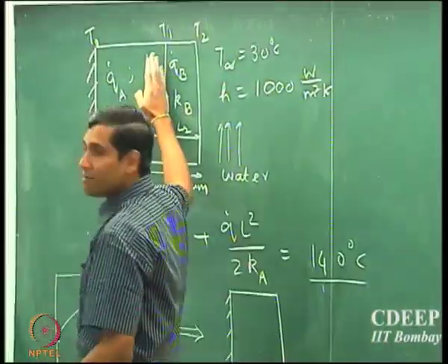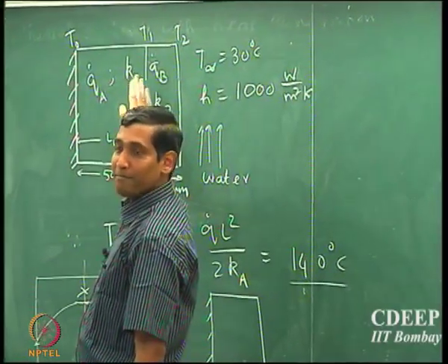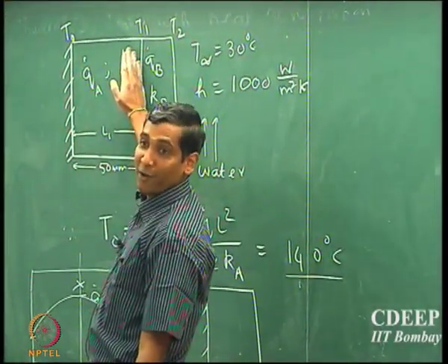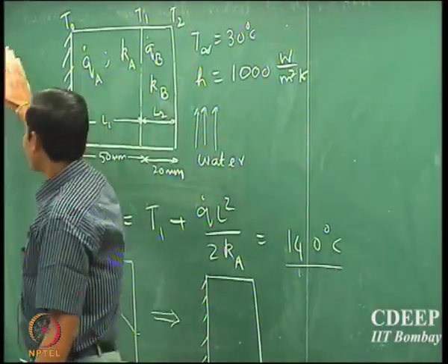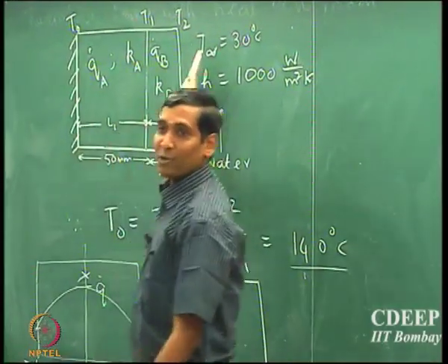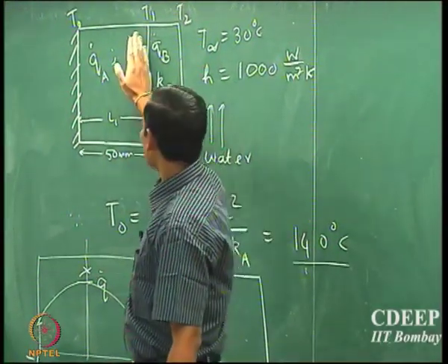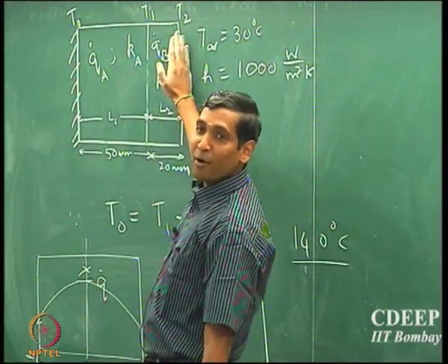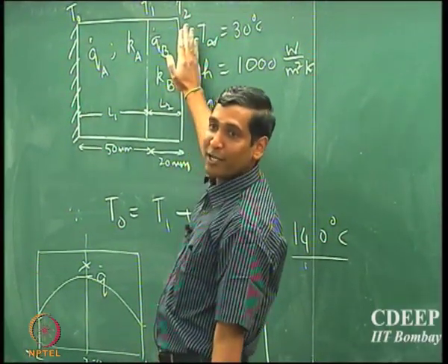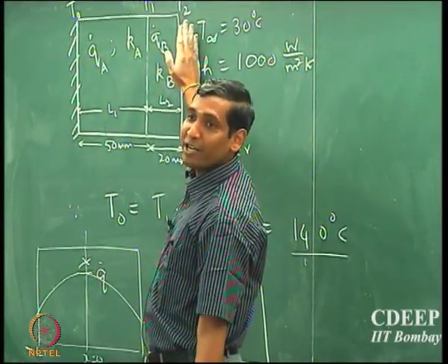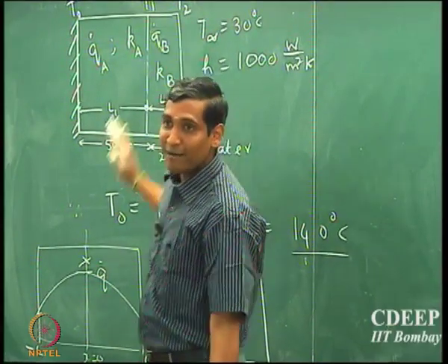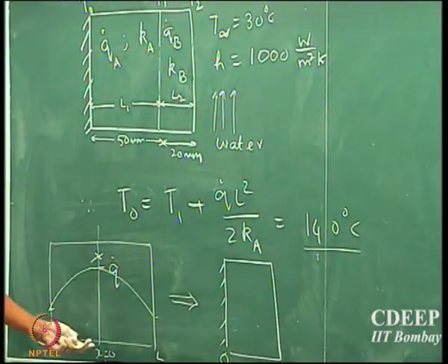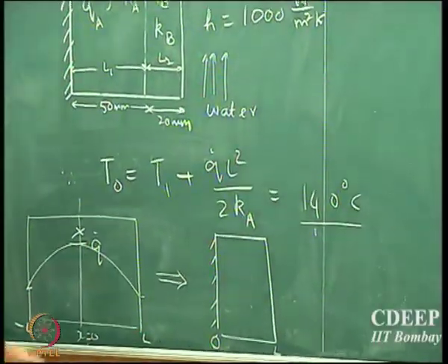How does heat come here? Because of conduction inside the slab. But we are looking at what happens at that interface. Because there is no heat that is leaving on the other side, everything has to leave through this side, and so whatever comes here should be the total amount of heat that is transported in the second slab, because there is no heat generation in slab B. Clear?